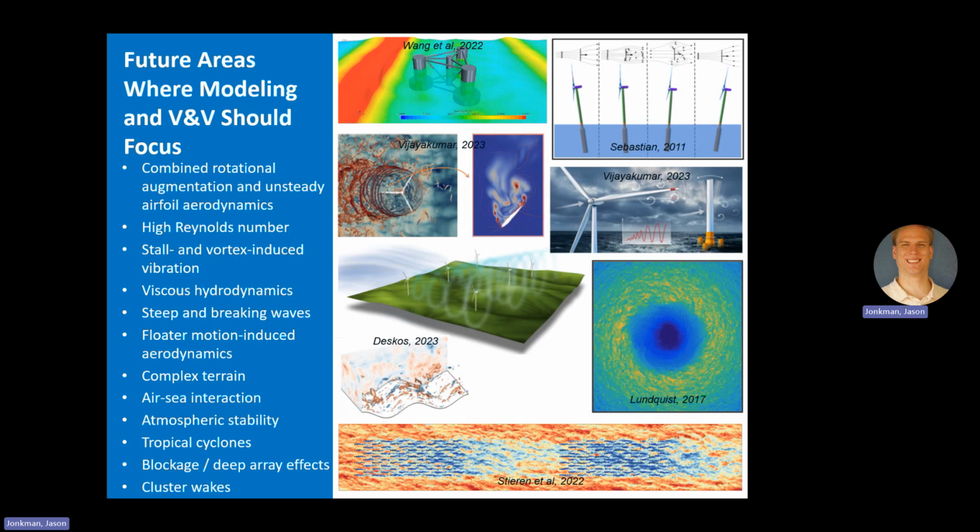But the first one there is early airfoil data. Again, these are lifting line models. We're not doing blade-resolved simulations here. So the question is always how to go from my 2D wind tunnel test or XFoil or RFoil to something that applies on a real wind turbine. The two issues there being rotational augmentation and unsteady airfoil aerodynamics.